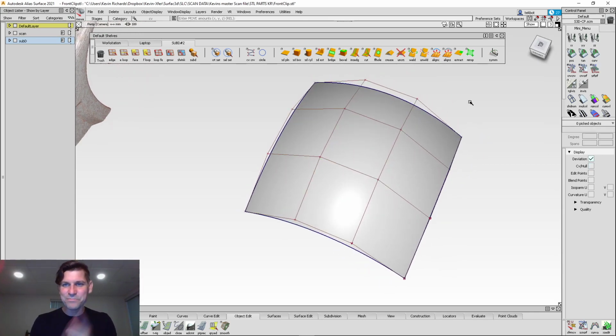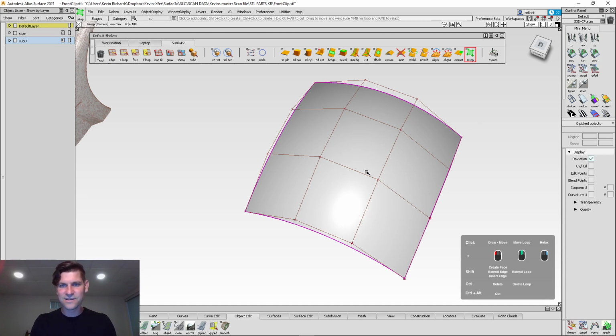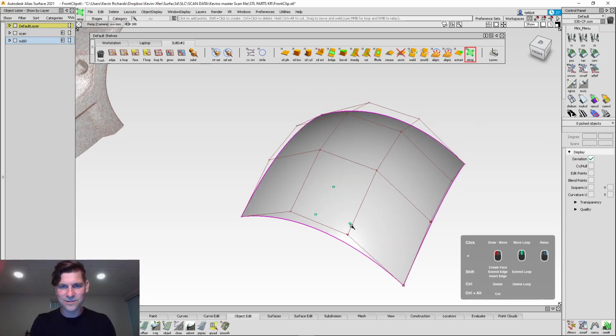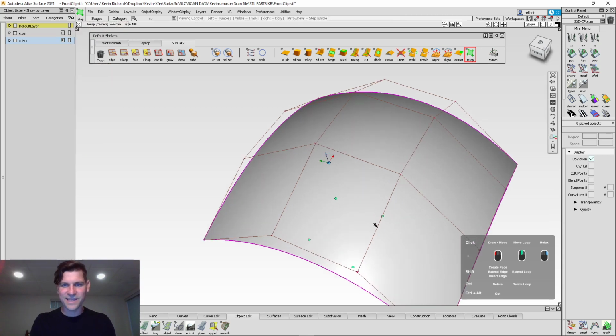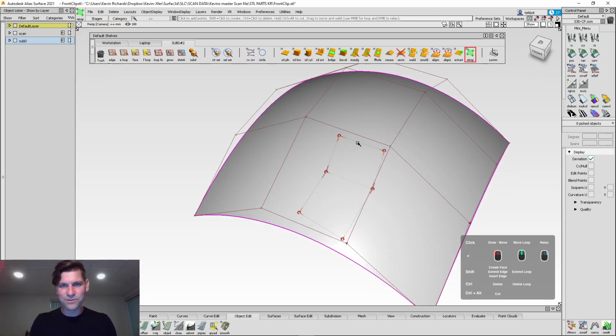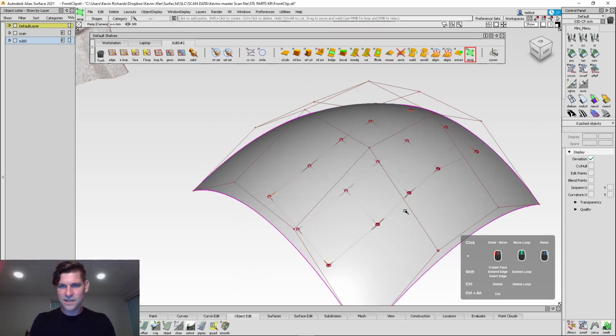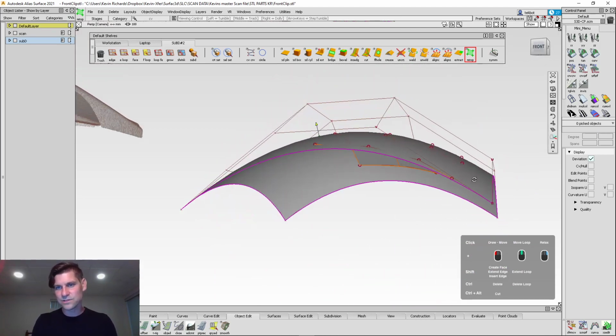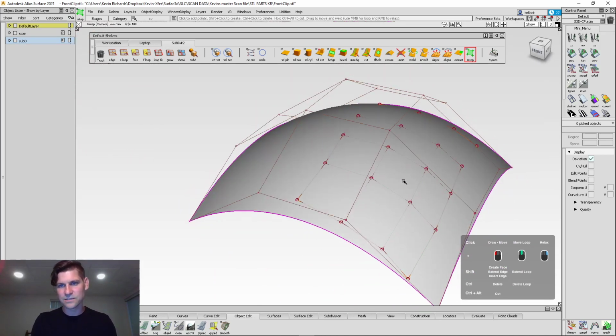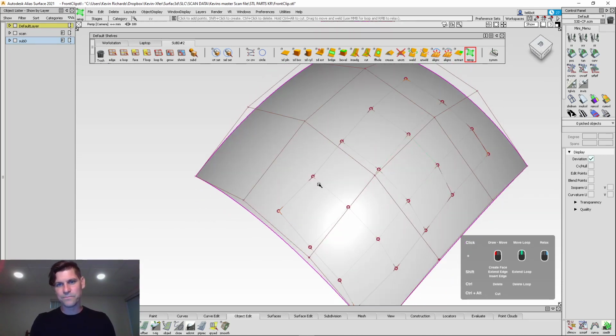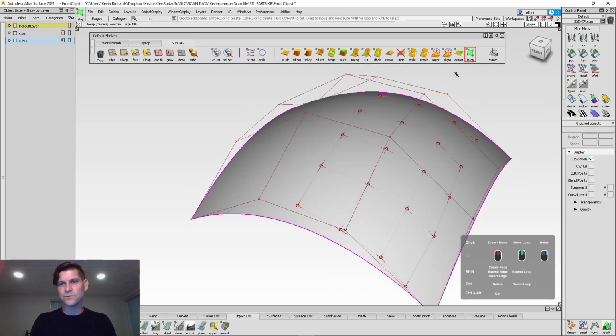And I'm pretty sure, if I have this as my target, let's try it. Can I click on this NURBS? Oh, dude, look at that. Sweet. And then we'll pull this out. Let's just create, yeah. Awesome. Middle mouse button, drag in that. Notice it's sticking to the surface. The cages, let's relax some of that, straighten it out. Sweet. And then one of the key things I would want to do, let's try this.